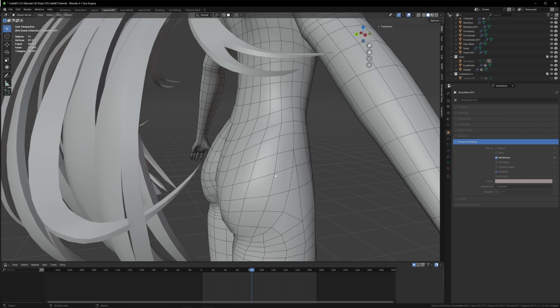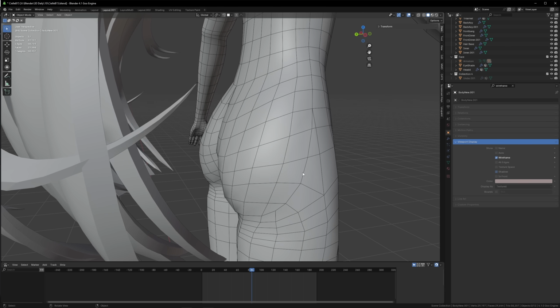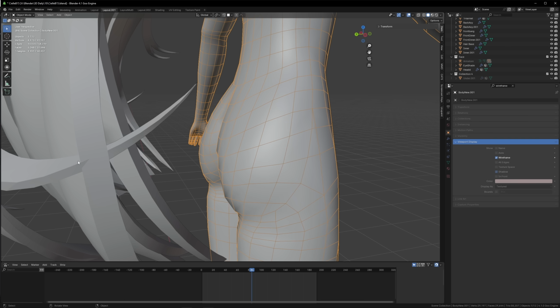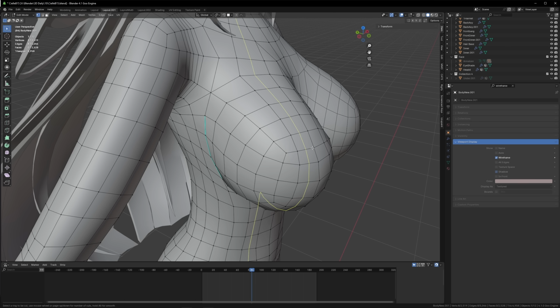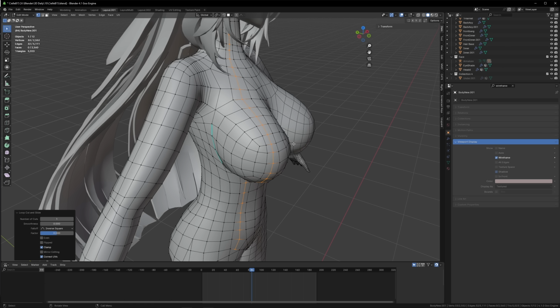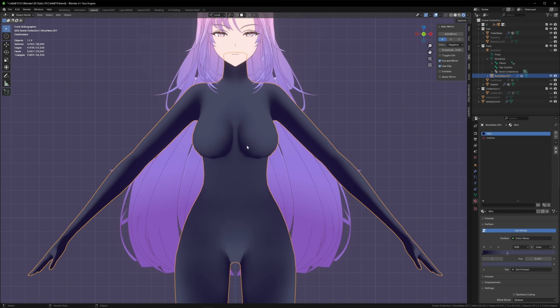Depending on the density of your pre-subdiv mesh, the resulting post-subdiv may not have enough loops to support good curvature on the mesh, leading to jagged forms. Now, we don't want to loop cut all the way so that it goes all across the entire body like this. So what do? The solution is actually pretty simple.